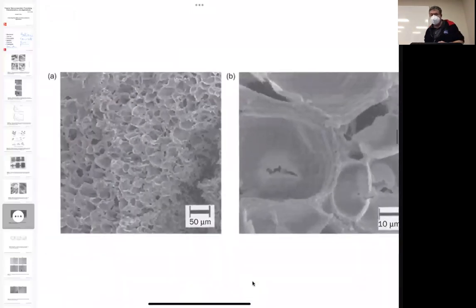And then this is actually, once you've taken your nanomaterial, now you burn it out. You burn out the polymer. If you don't apply any shear forces, whatever that nanomaterial was, this is sort of the structure it was when it was dispersed. It's not exactly, because it had to give room for the gases to come out. But we see that it's burned out right here, and so there's some collapse of the three-dimensional structure. But you can see that it has a three-dimensional dispersion throughout the entire system. And again, this is thermally removed out of the material.